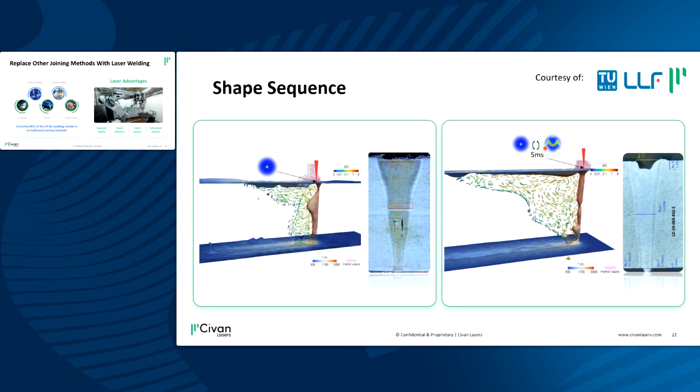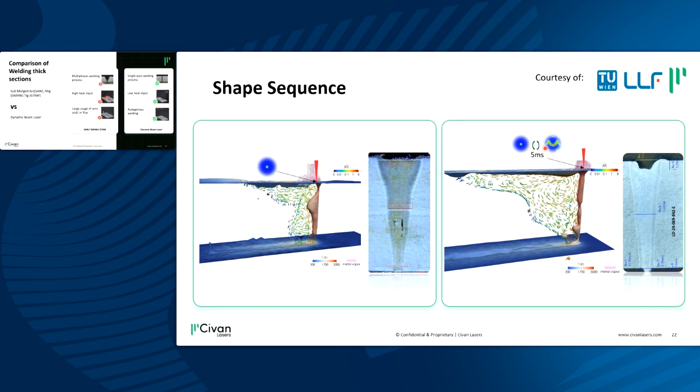But the issue with that is that it's very challenging and not possible for all of the different applications. Just to give an example, when we try to apply laser welding in thick sections, we can find very common defects such as root cracking or porosity, and most lasers are challenged to solve this. But as I will show you soon, when we start to apply these beam shaping methods, we are able to solve and overcome many of these challenges.